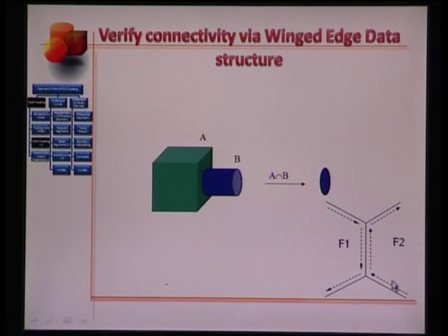Now if you recall, for any valid solid, polyhedral or non-polyhedral, with different surface patches stitched at the common boundaries, a valid solid will be one for which each boundary edge will have not more and not less than 2 faces incident to it.